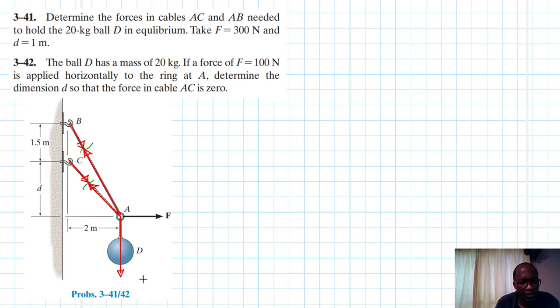What else? So here down, we have 20 kg for both, so I can indicate it. So say 20 kg times 9.81, which is the acceleration due to gravity, so that we find the weight. So 20 by 9.81 gives us 196.2 newtons.